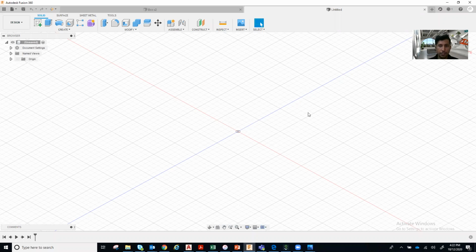Fusion 360 is a parametric software. Parametric means either you can specify the dimensional inputs as a formula or you can specify it later. That will help you in future whenever you are supposed to edit, so it will become very easy. For example, I'm designing a laptop of 13-inch size.